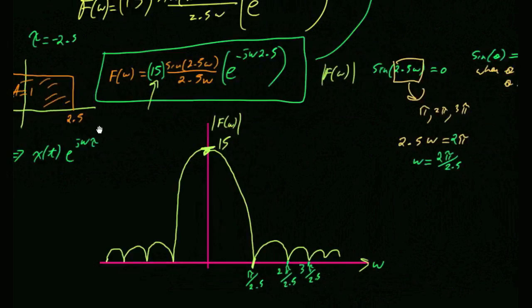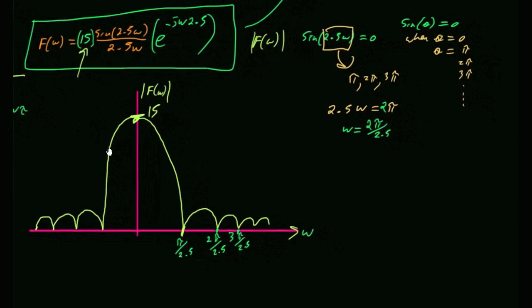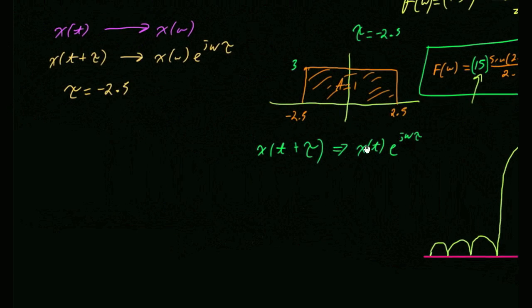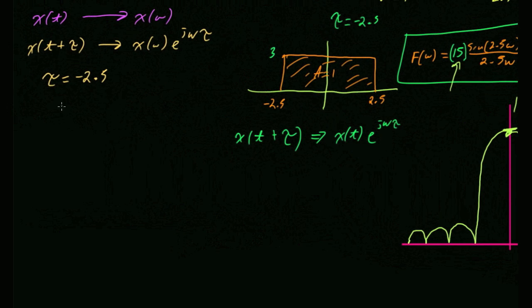You're not going to stick the negative in there, just put the... Right. I'm not doing negative of a negative. See, this is one of the advantages of having taught this class many times. I've tried teaching this by saying, let's pretend the shift is t minus tau. Then the rule becomes e to the minus j omega tau. And then people look at this and they're like, well, it shifted to the right, so is it tau equals minus 2.5 or 2.5? And everybody gets confused and loses the minus sign.